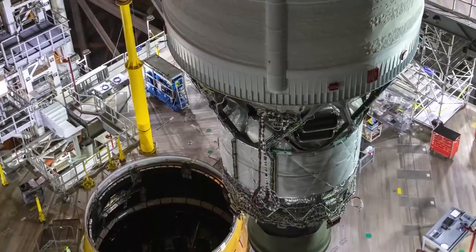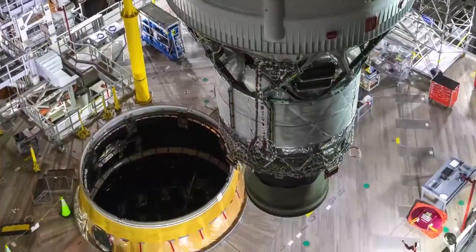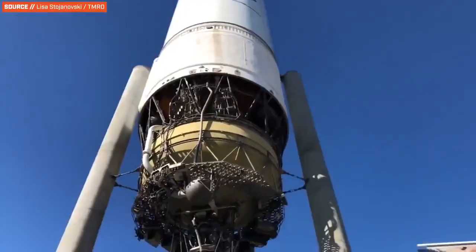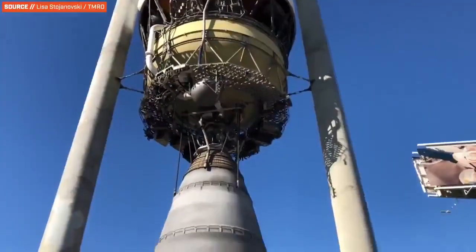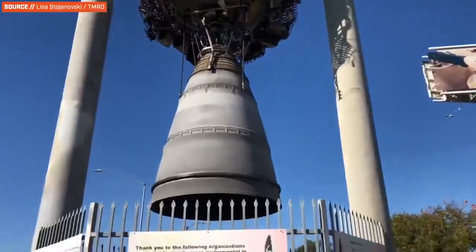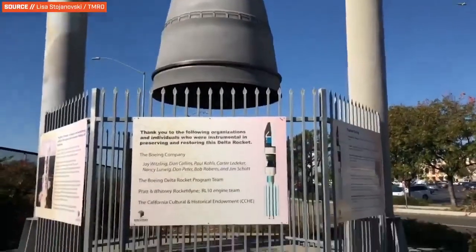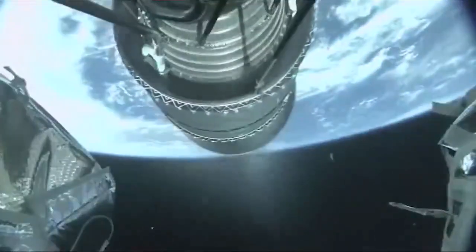These engines can reach ludicrous levels of efficiency. In fact, the RL-10B2, which utilizes the expander cycle with Hydrolox propellant, reaches 462 seconds of specific impulse. This is about the upper limits of what's even possible for chemical rocket engines.